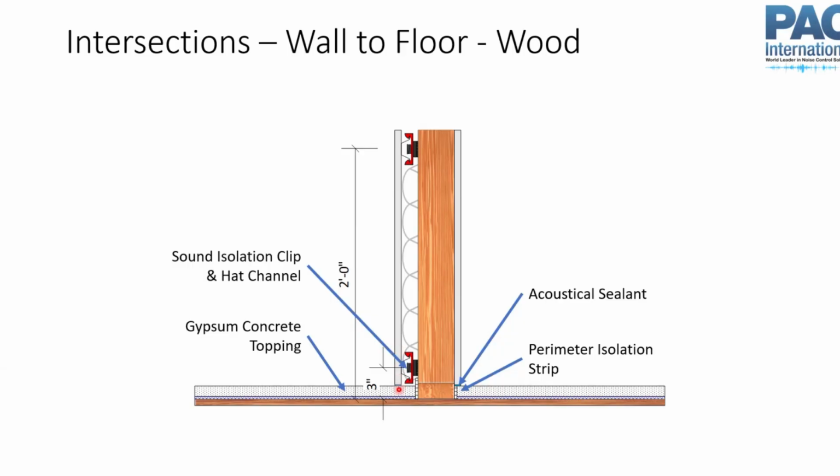We don't want to create a rigid connection between this and this. And we don't want a rigid connection between the gypsum concrete and here, because that could transmit sound across, or it could transmit sound up into this drywall, right? So everything here is isolated, right?